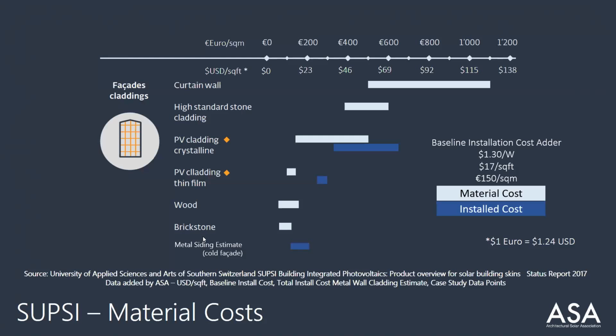And then just as a quick reference, where did Lumina fall? The material component of Lumina, meaning the BIPV system components, the things that actually make the wall, not the electrical generation side of things, but the installation labor to get the modules in place was around $38 a square foot all in. And, sorry, that was the material cost side of things, but when you add the installation, it was around $60 a square foot.